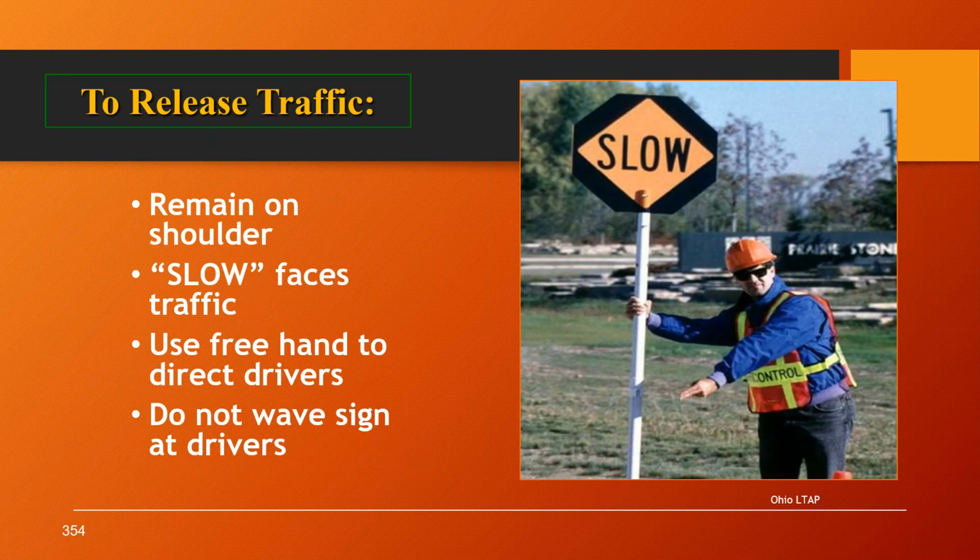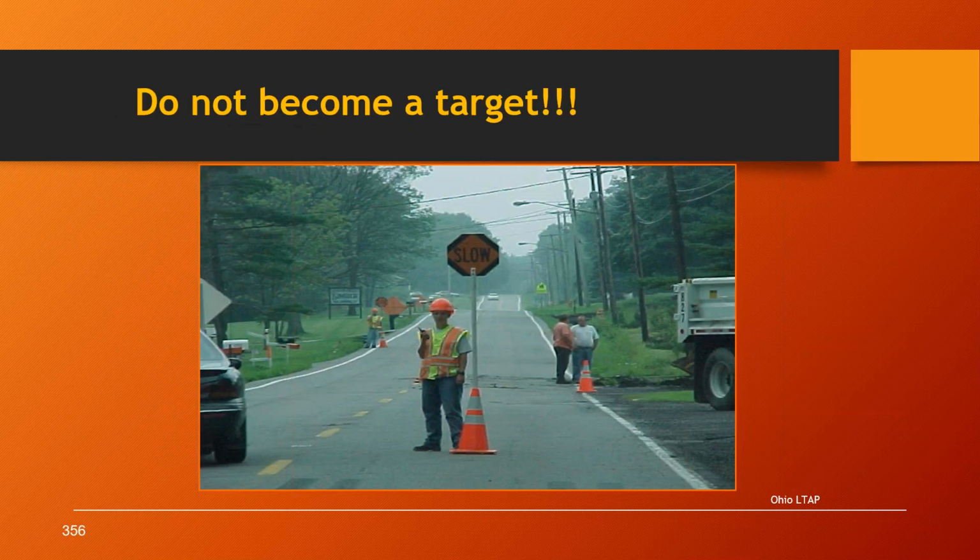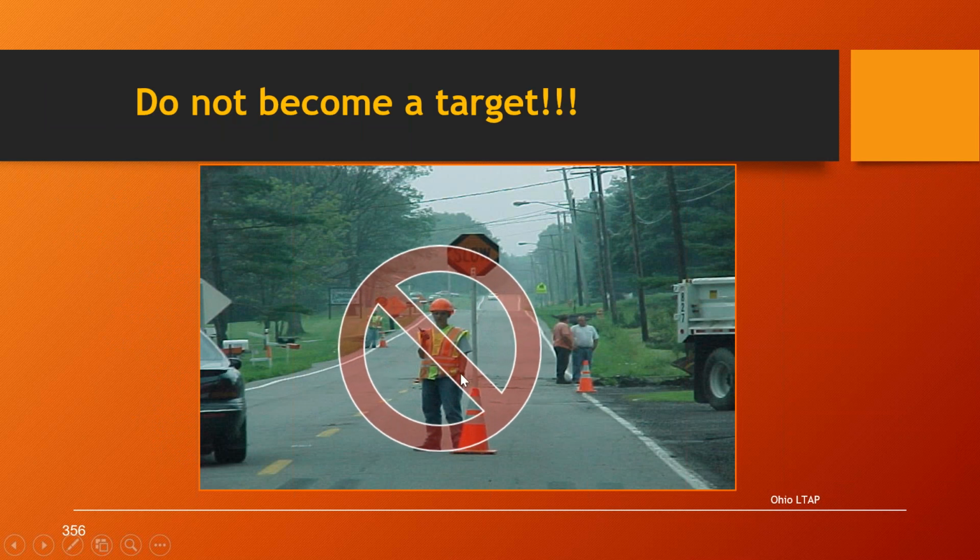Then to release traffic, as you can see, he's got a paddle turned to slow and he's pointing with his left hand out into the open lanes for them to proceed. We don't want you to wave the sign at drivers. That confuses them. So we don't want to see this, where the flagger is standing out in the middle of the road. Do not become a target.